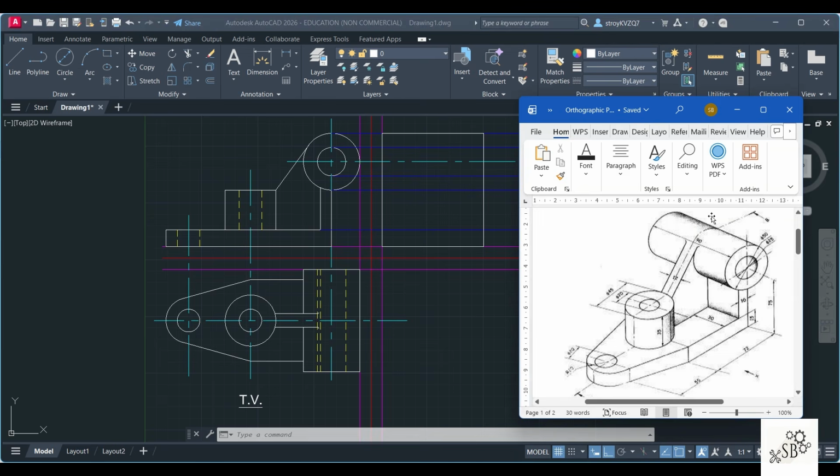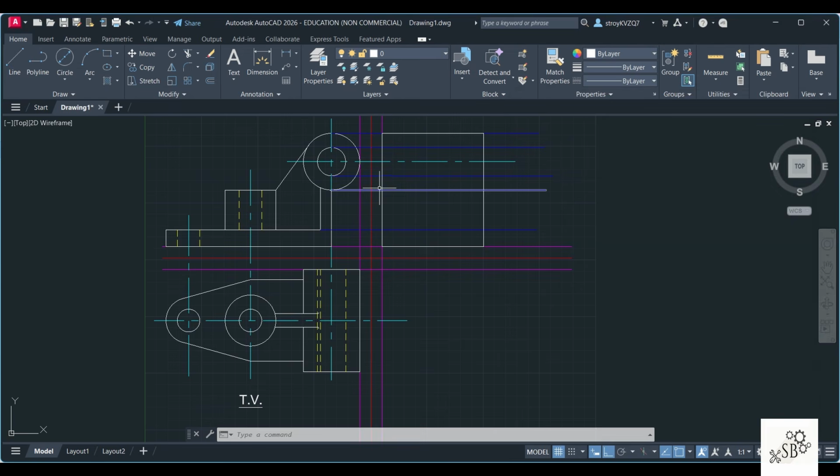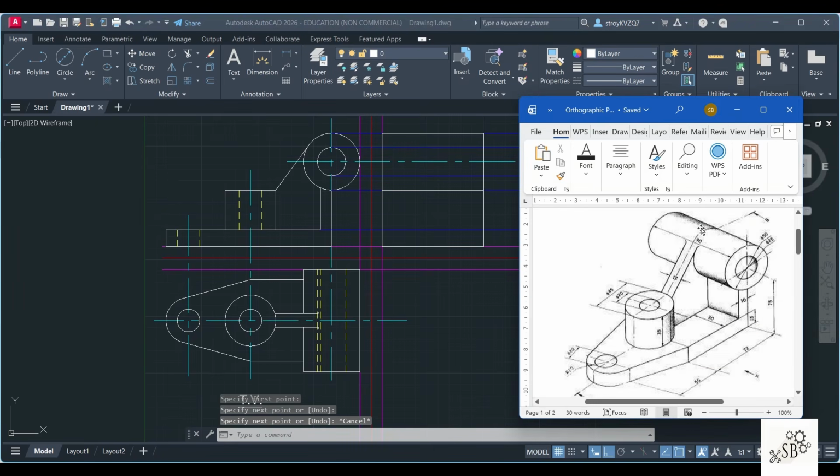Now I'll go to the diagram. When I see from this side, I can see this rectangle at the top first, whose height is the outer circle, so 50, and the length is 90. So this is already taken as 90, and this height has to be 50. As you can see here, this is the projection. So you can see this cylinder completely. I'll just draw this line. Choose line option from here to here. Escape. The top portion is your top cylinder, which we have drawn.